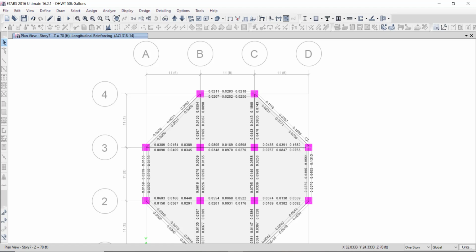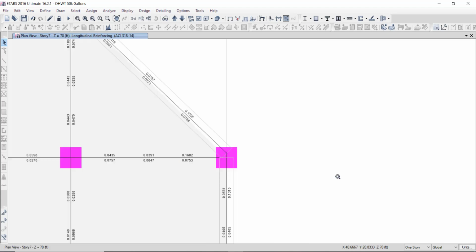This is actually not failed, because all the others are fine. It means there is good news: suppose this column is not working, your water tank will withstand with all the other columns. Suppose there are 4 plus 4 is 8, 10 columns, 11 columns. So this is a 12th column. This column we need to make in the corner. If we zoom in, we can see it. This column is out of the grid. That's why it is giving you incorrect results.